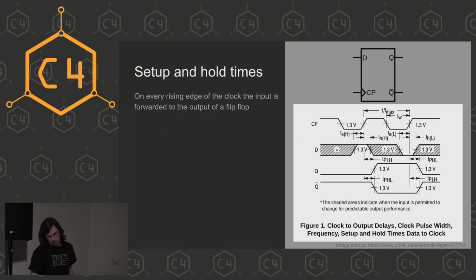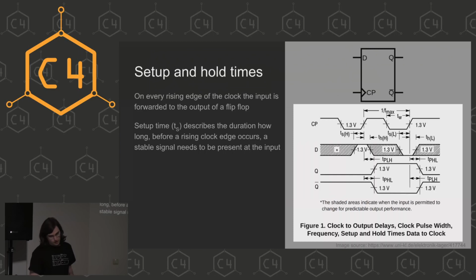Now, what about the setup and hold times? The setup time describes the duration, how long before a rising clock edge occurs that a stable signal needs to be present at the input. This is what you can see here. You can see here that the clock goes high, but at the time here, the signal on D already needs to be high even before the clock edge occurs.